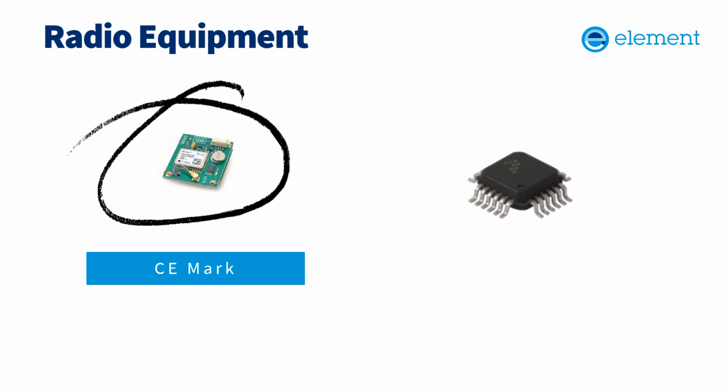In Europe, for example, a radio module is considered to be a radio equipment, so it comes under the Radio Equipment Directive. And also for North America, radio modules are specifically listed and can be certified in their own right. Now, there may be some conditions associated with that certification. It might say you must connect this type of antenna to it, and the manufacturer has to provide some very explicit instructions to ensure the integrator of that radio module doesn't affect the compliance of it in the way that they integrate it into the host itself.